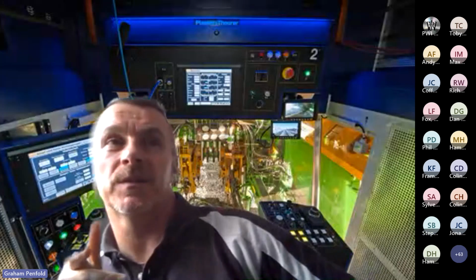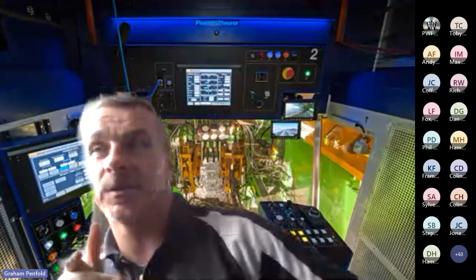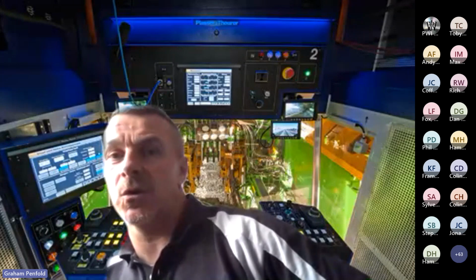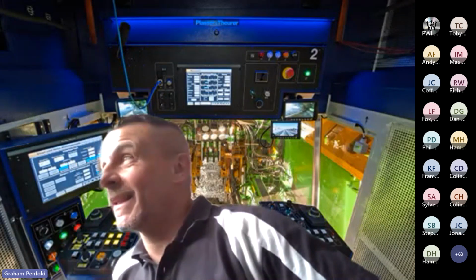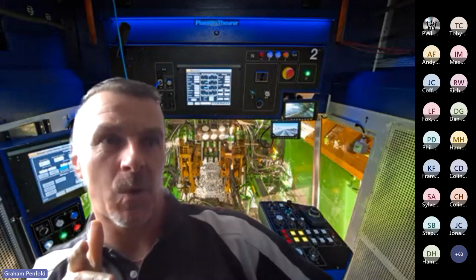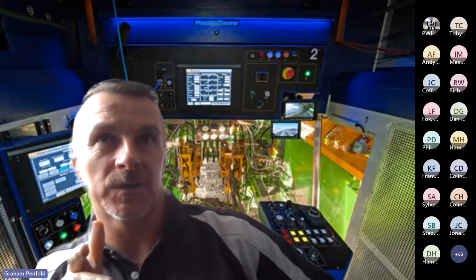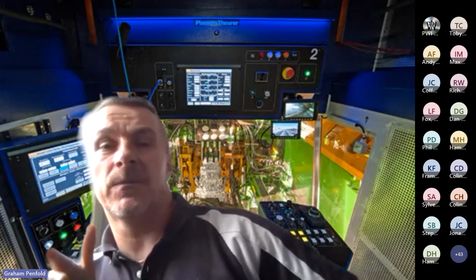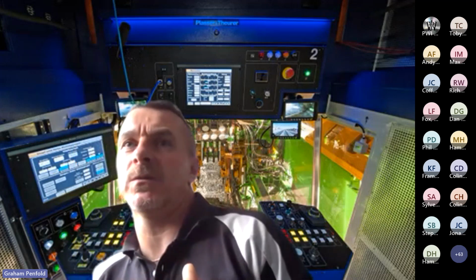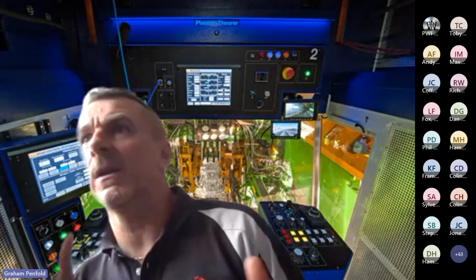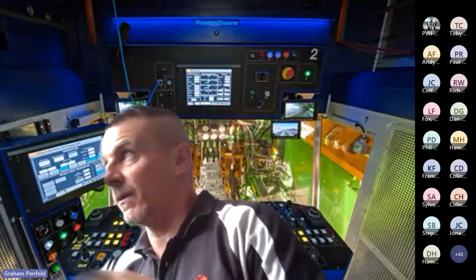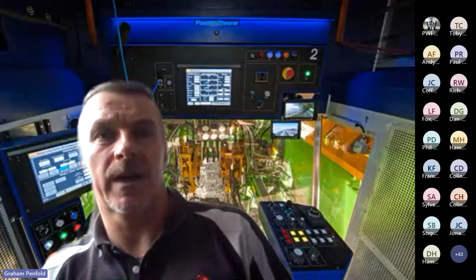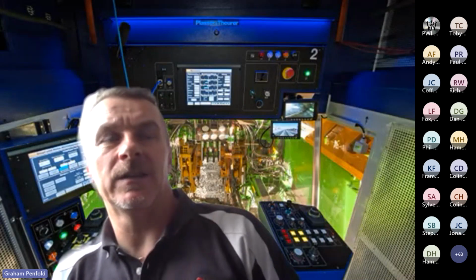So there's absolutely no reason why you couldn't apply it on steel sleepers, as long as you don't go silly with it and are a little bit careful with the lifts. If you look at some of the values, some of those overlift values are just 10, 12 mil, but that 10 or 12 mil makes a huge amount of difference to get to your design level for longevity. So the answer to the question is yes.